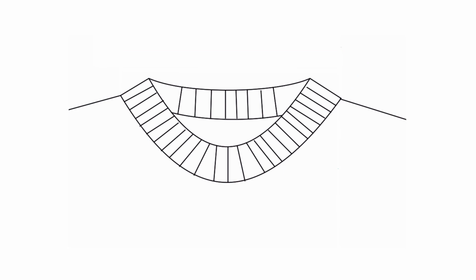Because of the stretchability in the knitted fabric, the edge-to-edge measurement may not be consistent, which often poses a problem, not only for the manufacturer, but for the quality inspector too. In case when neck measurement is provided edge-to-edge, and not seam to seam, it is difficult to calculate where the seam shall be placed, because the edge so formed at the neck is not straight, but is always at an angle.